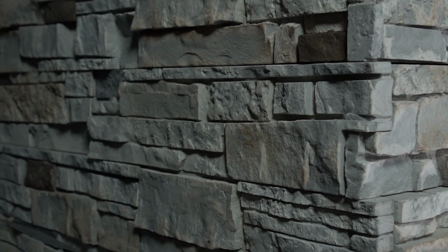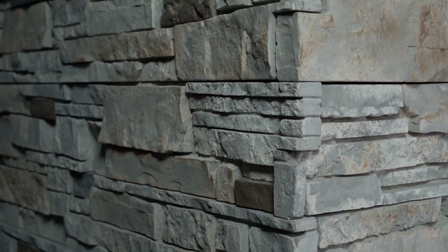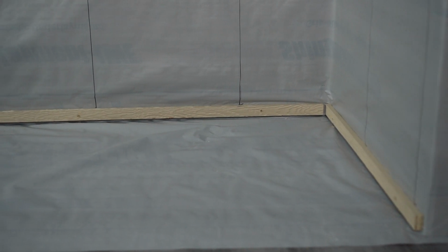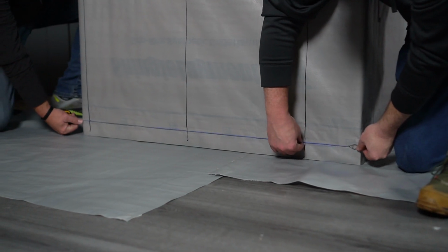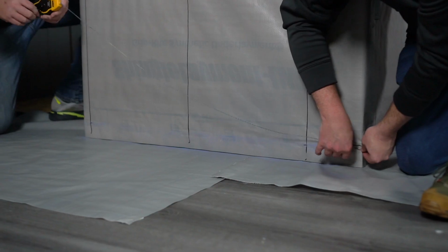As with most other brands of manufactured stone veneer, the bottom of the initial course of stones should be installed 4 inches above bare ground and 2 inches above a paved surface in an exterior application. To speed up the installation process of the initial course, a leveling board may be used. Once a starting point has been determined, snap a level line for a leveling board. The line represents the top back edge of the board.